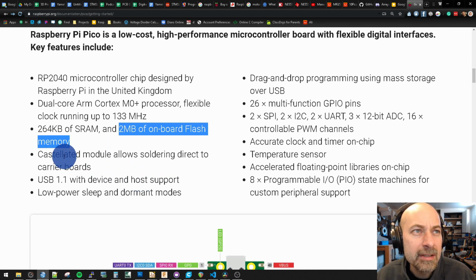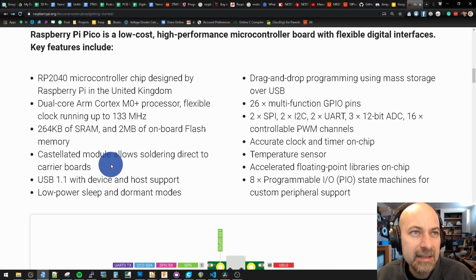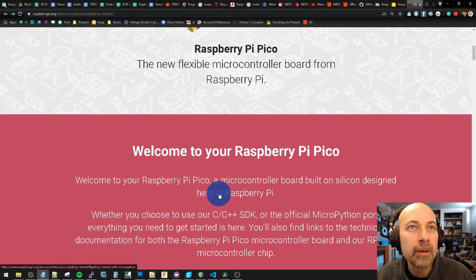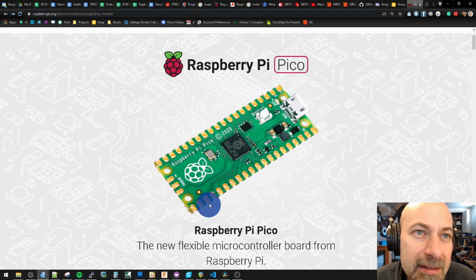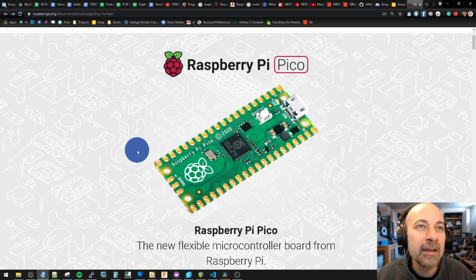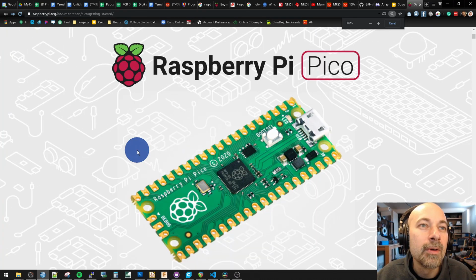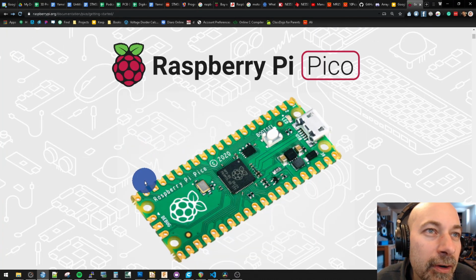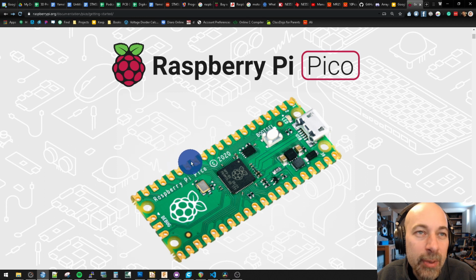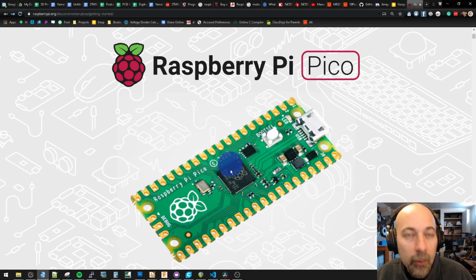Now here's one that we need to talk about too, it's a big one: this castellated module allows soldering direct to carrier boards. What does that mean? Well, it's castellated, it's kind of hard to see. Maybe if you go here, can I zoom mega in? Nope. Okay, well, right here, there's a curve. You see that? There's a concavity to all these pins. So you have the circle where you stick your normal headers if you want to put this on a breadboard or whatever, which is how I have to do it with the Blue Pill.